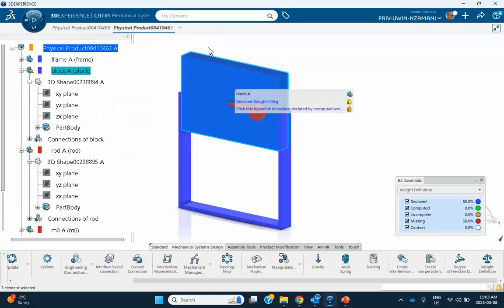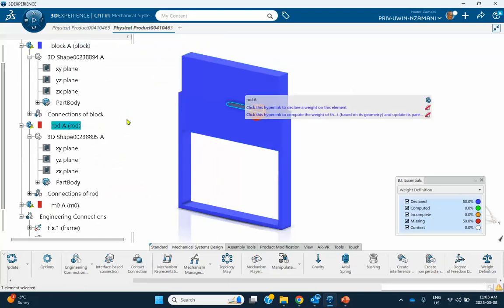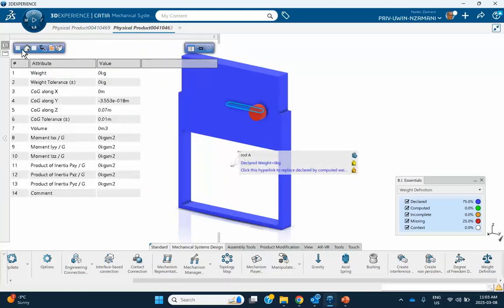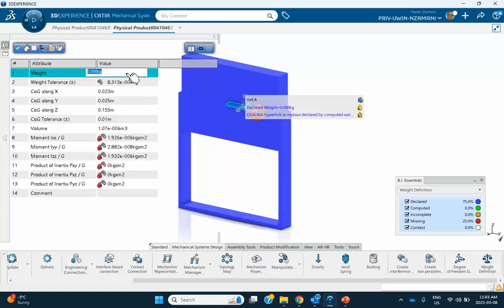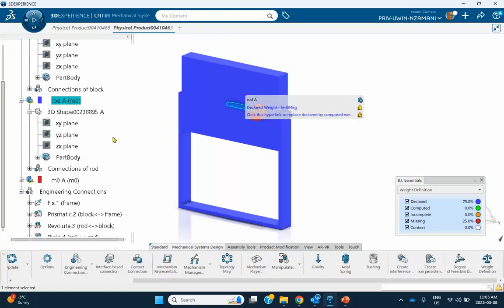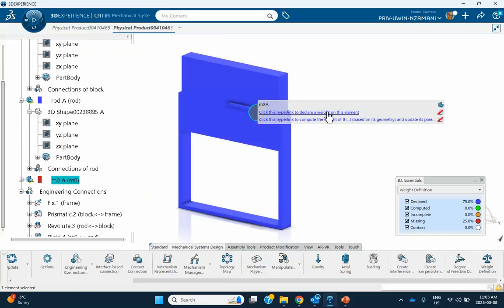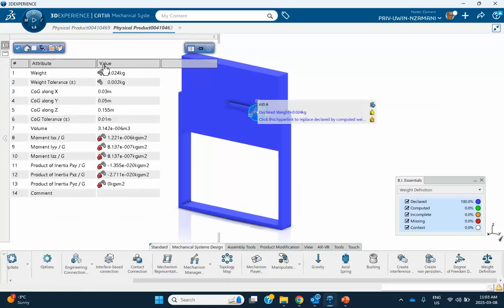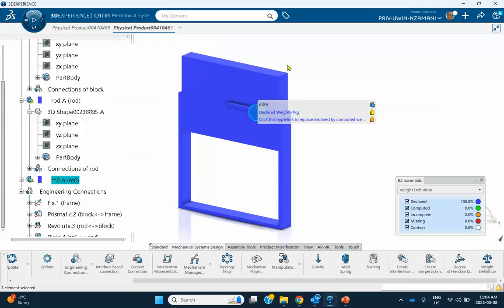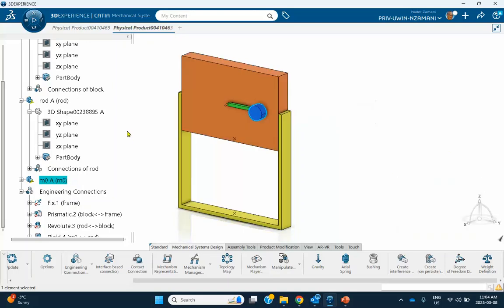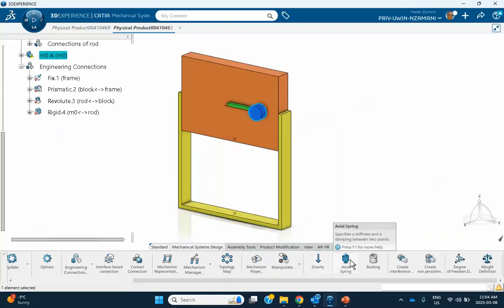Okay. Click on the rod, click on the link, make it out of steel, and make it extremely small, for example, 0.0001. Pretty much massless, you can see. And good. And close it. And finally go to the mass M0, click on the link, make it out of steel, and change it to be 1 kilogram. Done. So we have defined the properties that we want. Okay, very good.